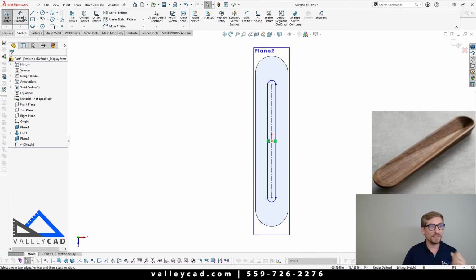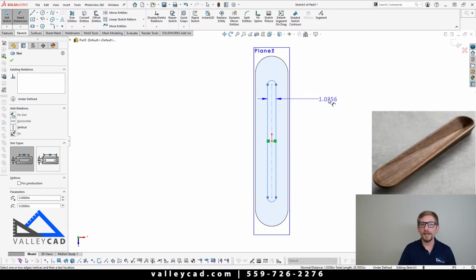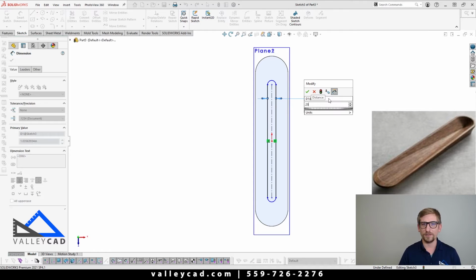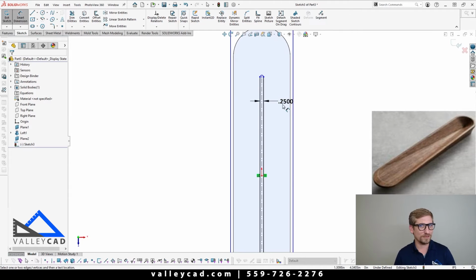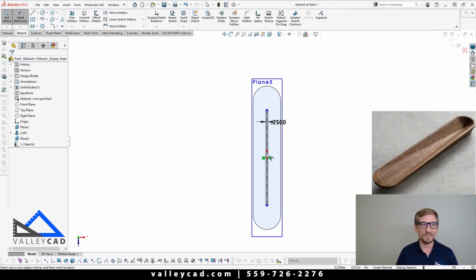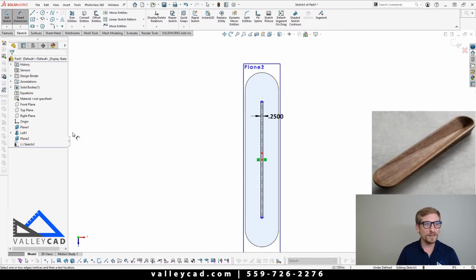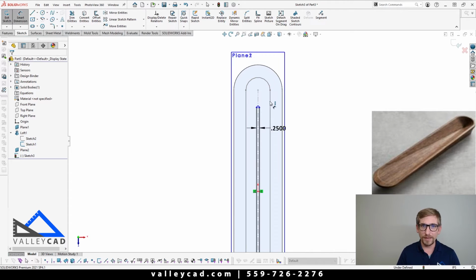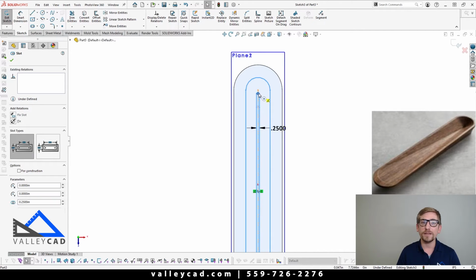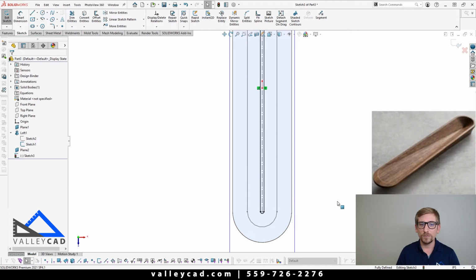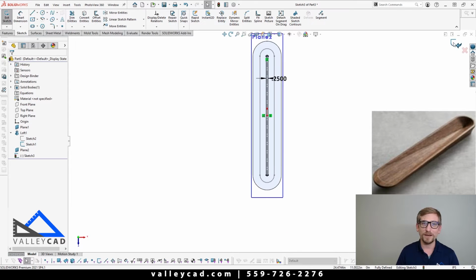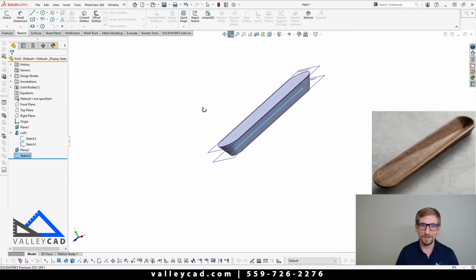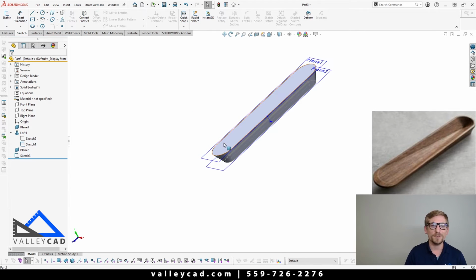So in this scenario, we're gonna set it up so that from here to here, it's gonna be at 1/4 inch, like so. Ooh, it's a little thin, but don't worry. We're gonna see what this will actually do for us. So 1/4 inch, and then from here, what I wanna do is simply see my sketch number 1. So I'm gonna say show to that. And then from there, I'm gonna utilize my existing sketch to lock this new one. And from there, simply say okay to that. All right, cool.